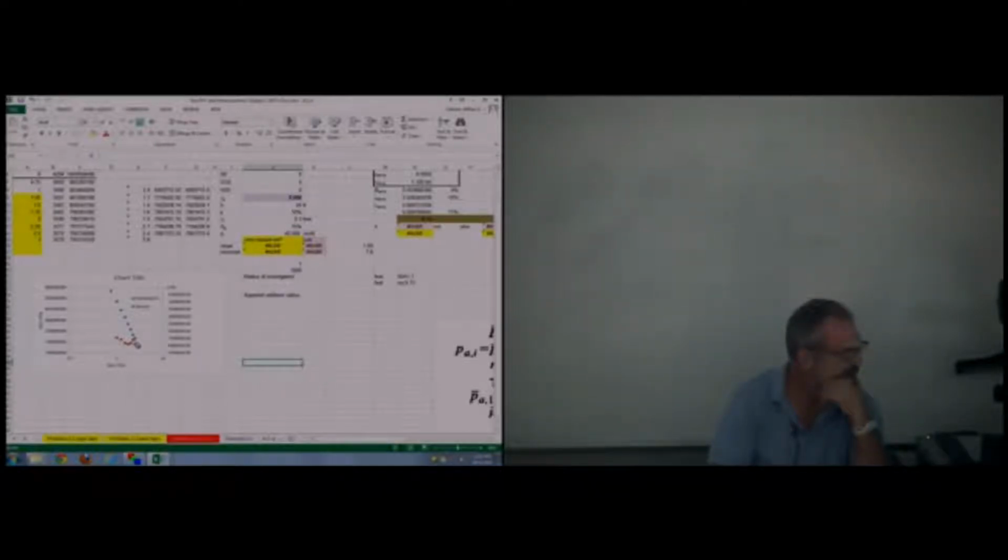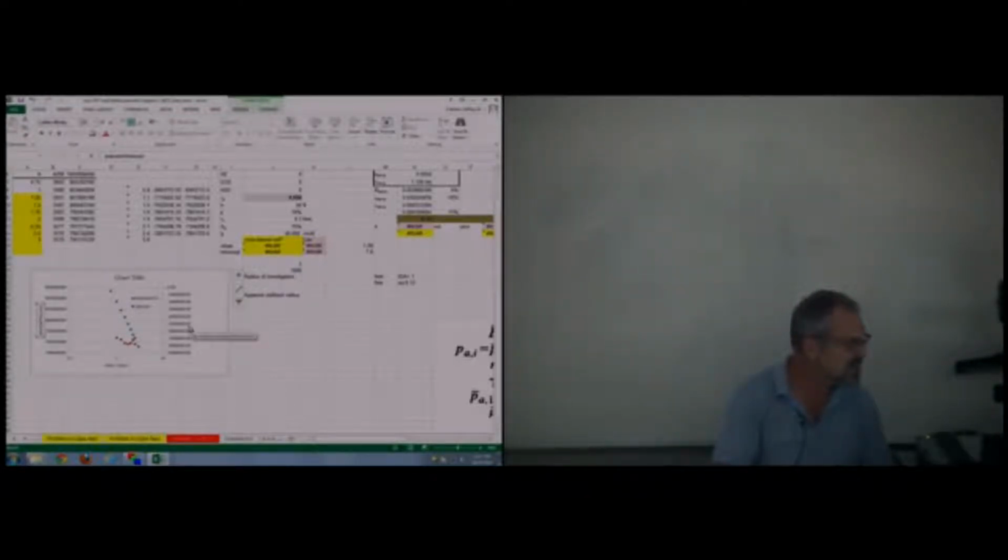And although that looks a little noisy, it's fairly flat, and you can see from our data, it looks like we got a pretty good straight line when we plot the semi-log of. This is a drawdown, so this is just time. Well test units are hours. And over here we have pseudo pressure. I'm not going to put down the units, but it's psi squared per centipoise. And over here we have our derivative.